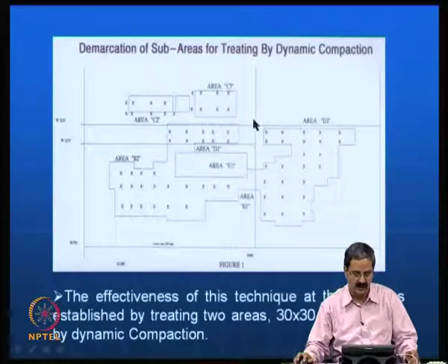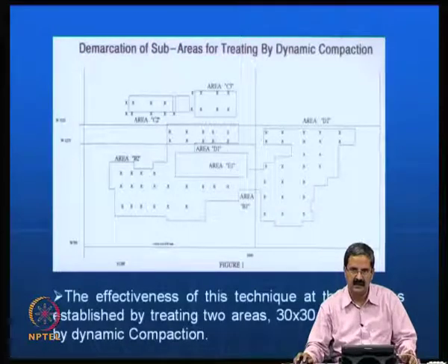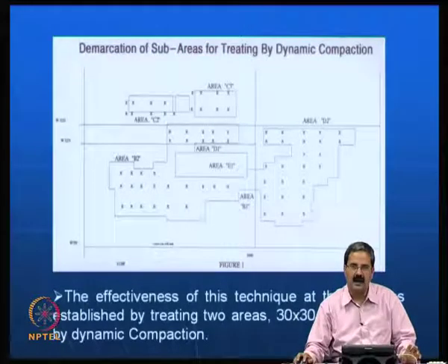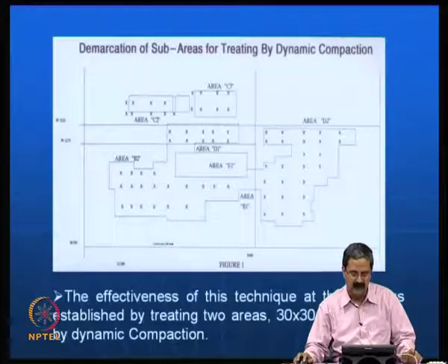It is very important to do a trial test in dynamic compaction, or for that matter in any ground improvement technique, because you will exactly understand how it is working in the field, and you can fine tune it also. If you are not doing well, or if the assumptions you made are not appropriate, then you can make some corrections in the design.